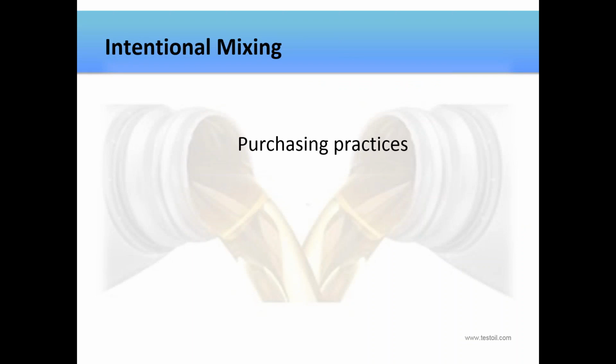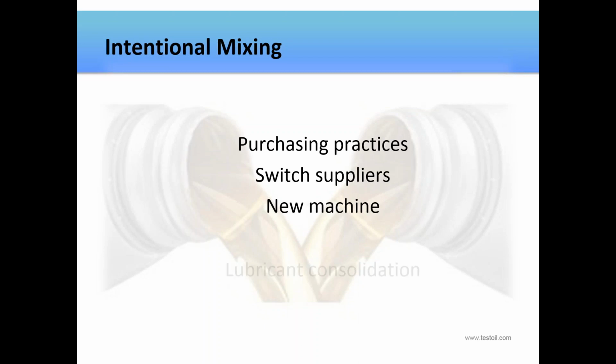So then when we go to intentional mixing, this can also occur for a number of reasons. It might be related to the company's purchasing practices, such as buying from the lowest bidder. It could be a change in lube suppliers, and this can necessitate switching to another product in order to consolidate. When receiving new equipment, it might be filled with an unknown lubricant.